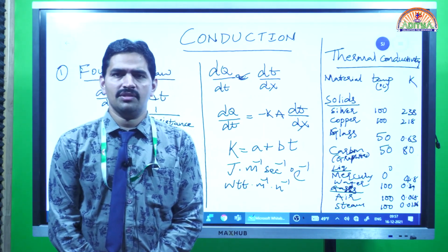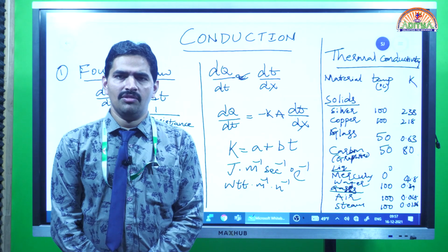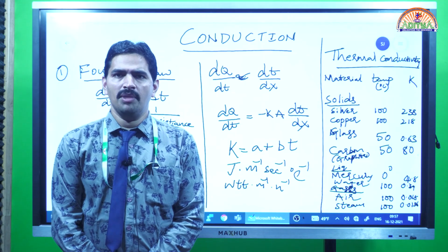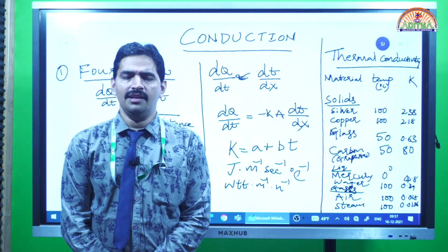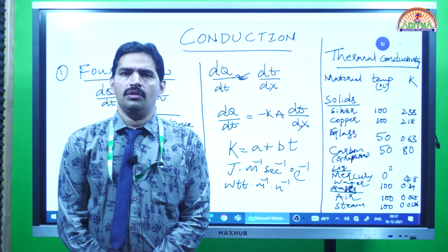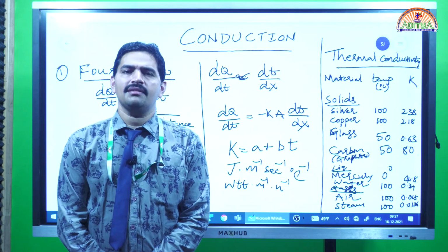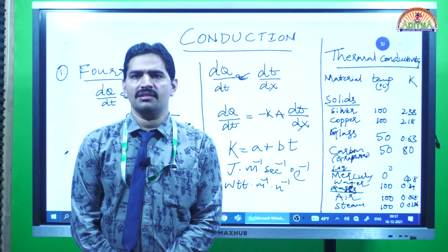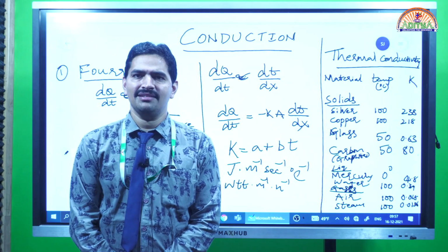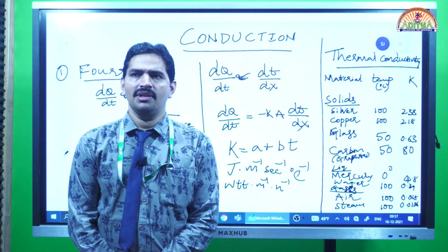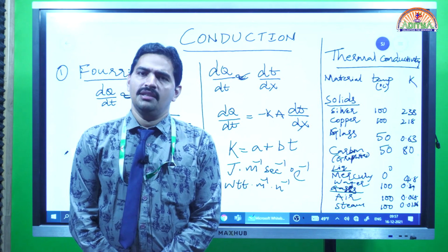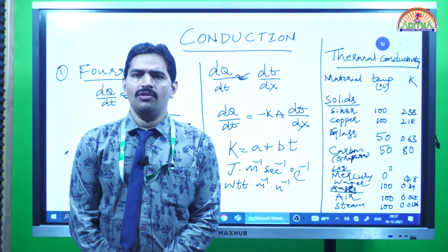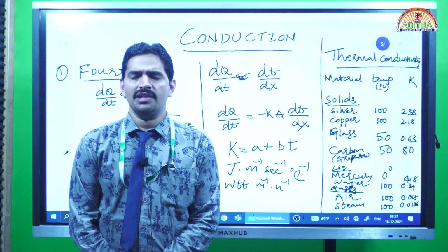Conduction means heat transfer from one molecule to another molecule in the medium, throughout the medium, by means of vibration. See here, there is no mixing of the molecules which causes the heat transfer. The heat transfer happens by means of vibration. One molecule absorbs the heat energy and vibrates. Because of this vibration, the heat is transferred from this molecule to another molecule. In such a way, from molecule to molecule, the heat is transferred throughout the medium.